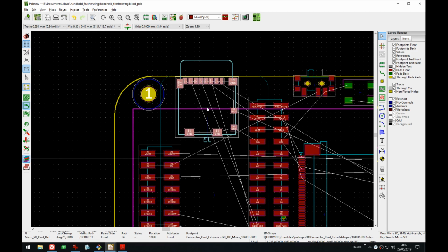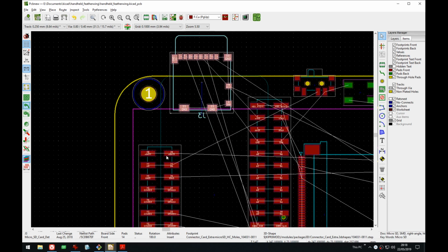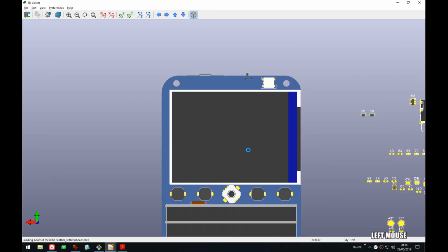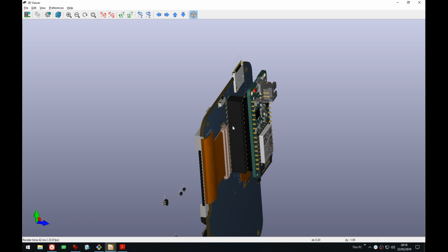Yeah, I mean, an SD card connector is not much taller than a QFN, and these connectors will be way higher anyway. Like if you see here, I don't know, it's annoying. It might not be this high because these are the standard height connectors, and I'm trying to look into half height because this is just ridiculously tall.